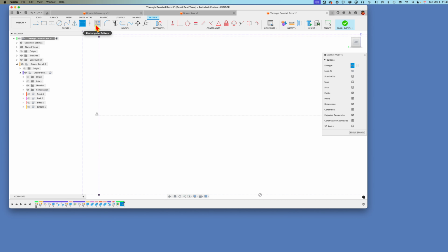And another handy thing I generally do is put a point, which is a sketch feature, right at the intersection of the front where I'm working on creating pins and the center of the pin line. So let's just put a point there, and then we're going to say this is coincident with that, and it's coincident with this. So it's right there at the intersection of those two lines. You can do that by just putting the pin on there, but it's so hard to tell that you've got an intersection with both of them. I prefer to do it off to the side and then use a constraint to bring it into conformance so I know it's at the intersection of these two lines.